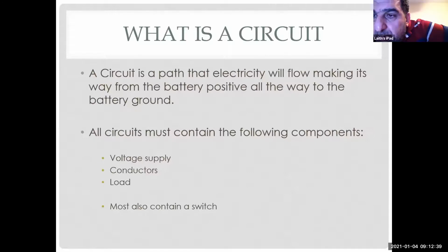There are relations between them. Right. So I have to have all three of those. And then the size of my voltage supply and the size of my load will dictate the amount of current flow. So if I put in more voltage, I can flow more current through the same size load, right? For example, 12 volts through 3 ohms would be 4 amps.